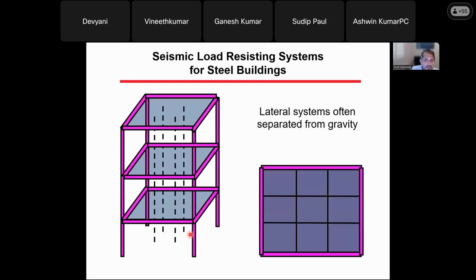What you have here, the pink solid lines, are the lateral systems. When the earthquake happens, all the force goes into these lateral systems, but the gravity systems don't carry any force. This is actually another layer of economy, because you don't have to make every single system a ductile system, or even design it to carry seismic loads. You can have only some frames in an entire building. Sometimes you'll have a very large building with only a very small number of frames which carry the seismic load. The reason you can do that is that the R factor gives you such a large discount on the total force that you have to design these systems for.